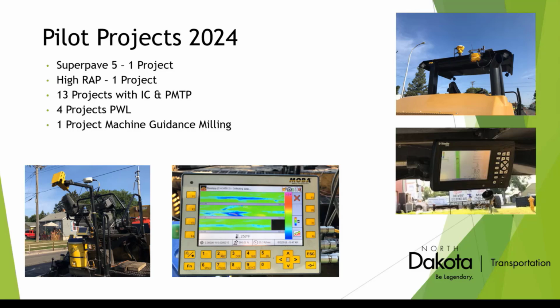But in this case, the point of reference you're going to use in this particular project is the LiDAR map of the existing road. So it's actually setting continuous crown and slope changes based on what finished slope you're trying to get and what thickness you're trying to take off the road, or nominal thickness.